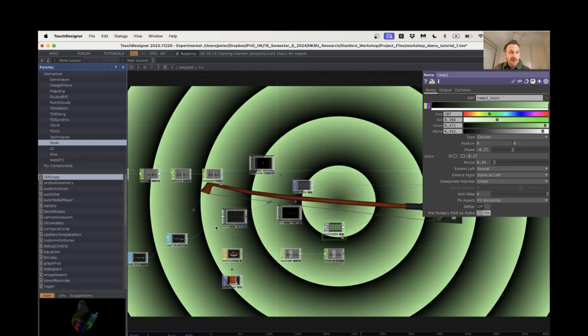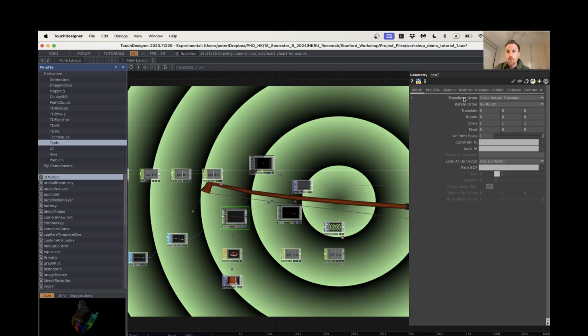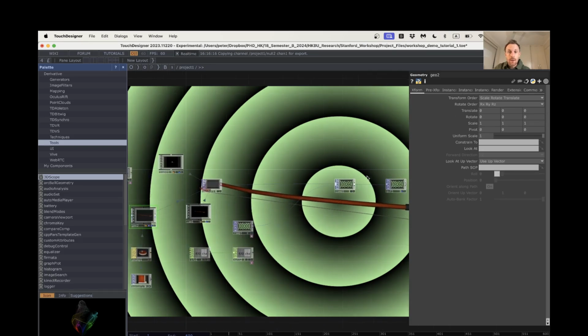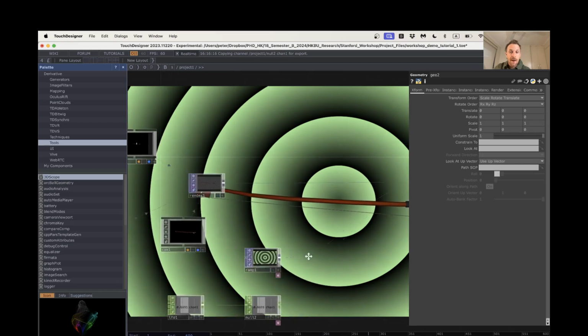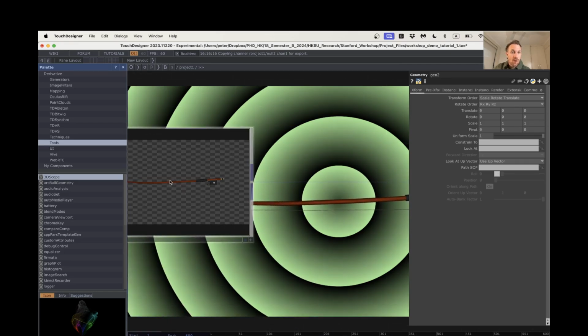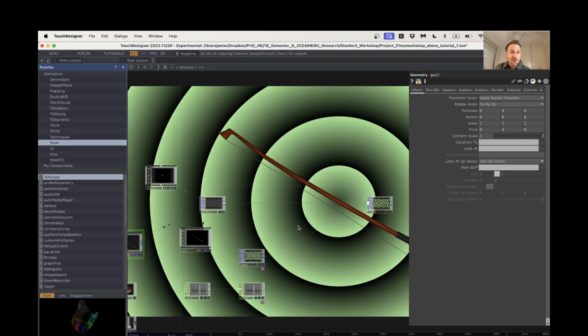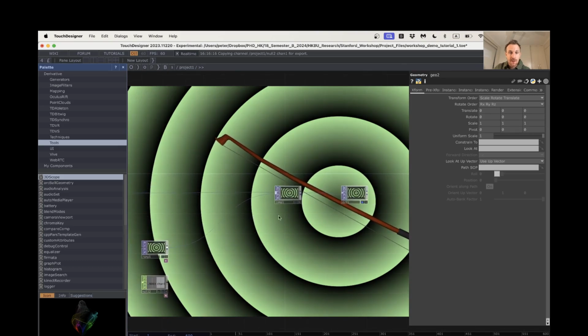We could either duplicate them in the 3D space with what's called an array or instancing, or we could duplicate it in the 2D space, because now that we've rendered it into 2D, we can just copy this series of 2D images, which to me has even less compute than copying the 3D.